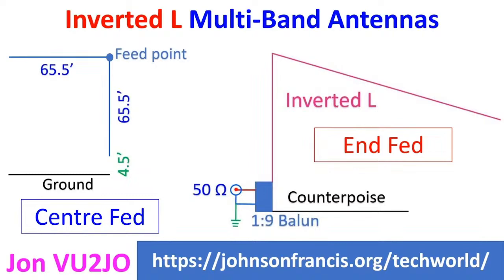Lowest end of the antenna will be 4.5 feet off the ground. As it is a complete dipole, it does not need a ground plane beneath it, unlike a quarter wave antenna. A parallel feed line of 450 or 600 ohms impedance and an antenna tuner are needed for multi-band operation.